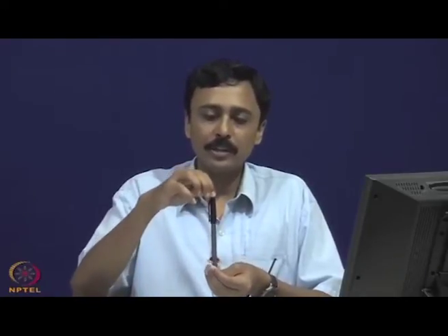But suppose you want to devise a procedure of non-destructive evaluation of the buckling load of a column experimentally. You can use this dynamic feature. You increase the load and look at the lowest eigen frequency, and when it reduces to a very small value which you can tolerate, you can use the expression of the variation of the eigen frequency with the axial load to find the intersection without actually destroying the column.